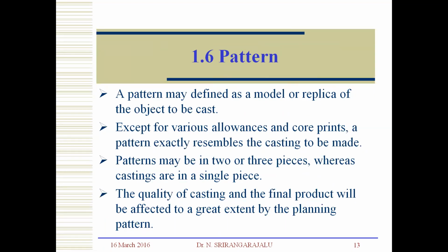Pattern. A pattern may be defined as a mold or replica of the object to be cast, except for various allowances and core prints. A pattern exactly resembles the casting to be made. Patterns may be in 2 or 3 pieces, whereas castings are in a single piece. The quality of the casting and the final product will be affected to a great extent by the pattern planning.